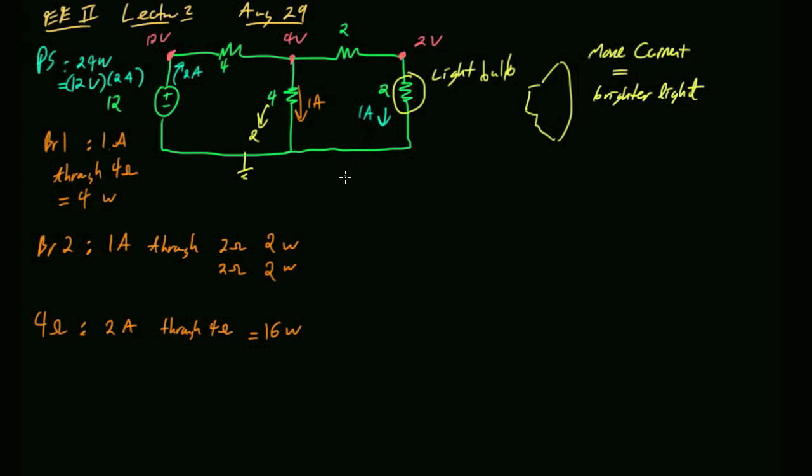Yeah, the supply is producing 24 amps. The resistors are consuming a total of 24 amps, so there's no power that's been unaccounted for. So that's good. Now that we remember the circuit, let's go and change this from a 4 to a 2. Okay, so let's resolve that circuit if we reduce that 4 ohm resistor to a 2 ohm resistor.